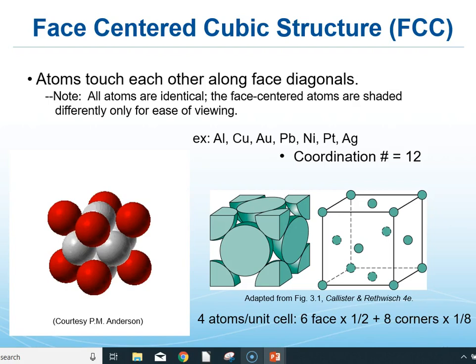These are unique in that a face-centered cubic is a close packed structure. Hexagonal close packed and face-centered cubic are the 2 densest, or most volumetrically dense, crystal structures that can be achieved with single atoms, and generally the densest that can be achieved, period. So these also tend to correlate with higher density. Definitely you see lead there and platinum being dense. Those also have high atomic weight, but it's another contributing factor.